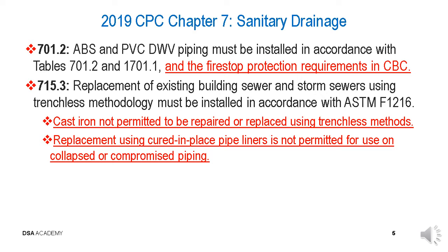Cast iron is not permitted to be repaired or replaced using trenchless methods. Replacement using cured-in-place pipe liners is not permitted for use on collapsed or compromised piping.